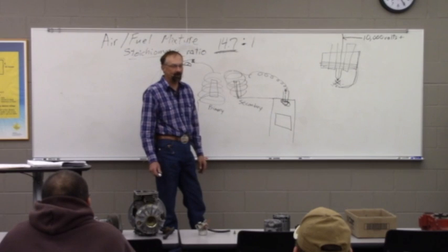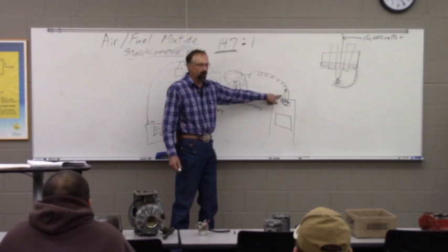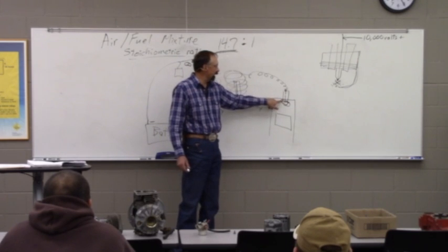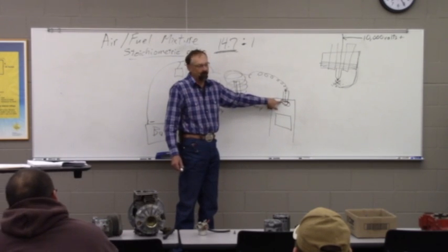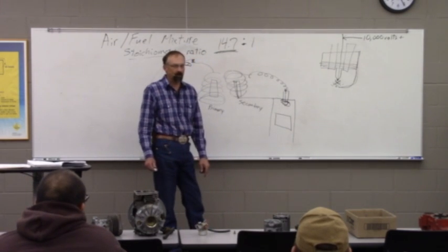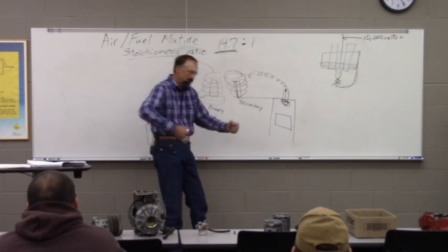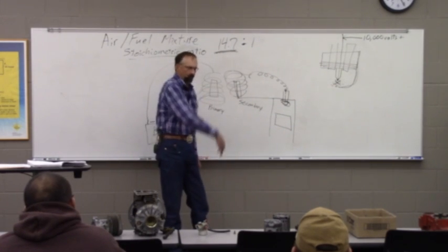The other thing that is critically important in modern engines is you don't put these in with your ratchet and your breaker bar, you put them in with your torque wrench. The exact tightness that these are put in is pretty important these days. These spark plugs are not nearly as robust as they were at one time, and you used to put them in about that tight and it was fine.